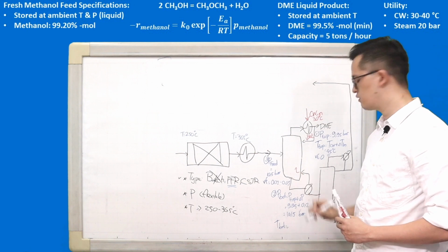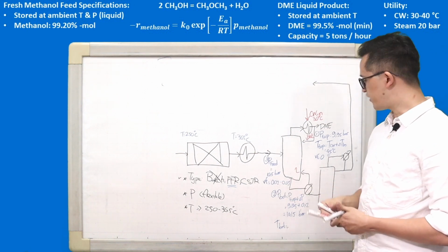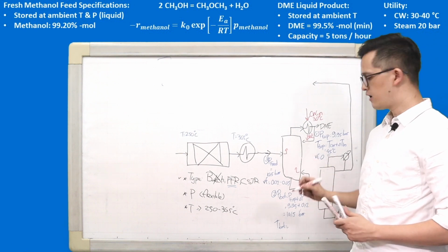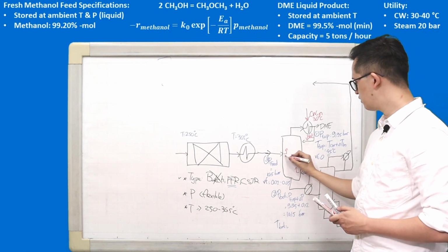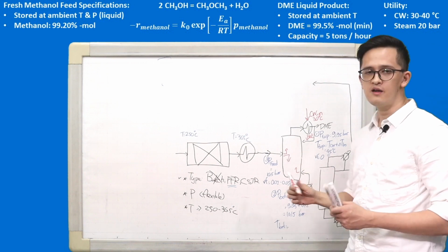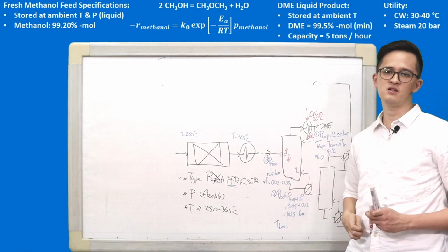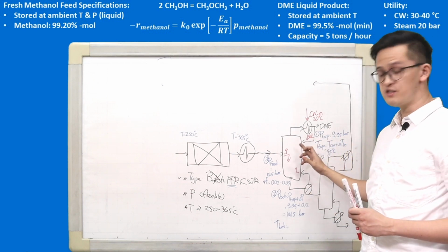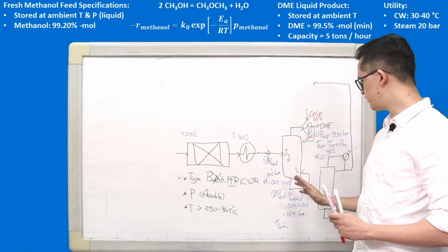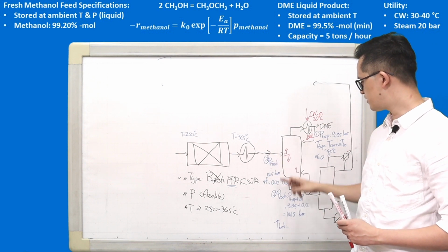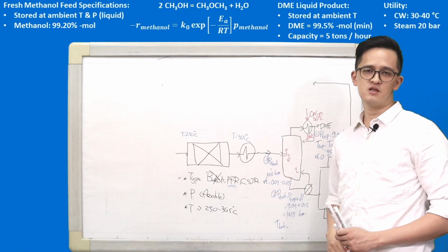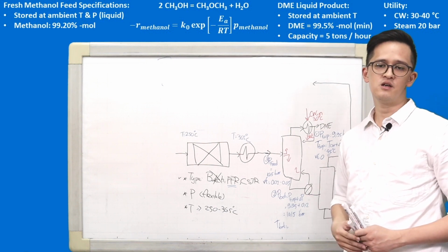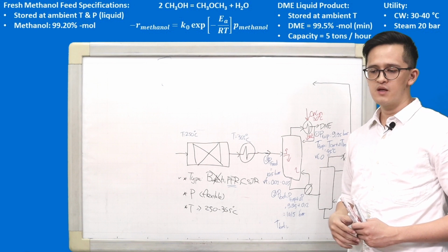So that some of the vapor will go directly to the top, and most of the feed will go to the bottom, and that helps your equilibrium inside the distillation column. Okay, the top conditions are finished, the bottom conditions are finished, and the feed condition, pressure, and vapor fraction complete the material balance.